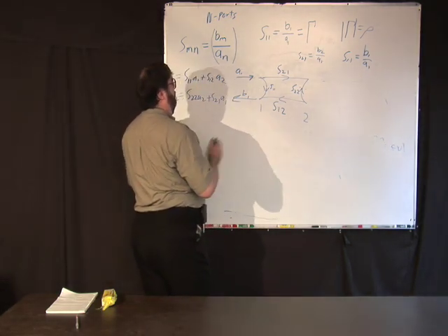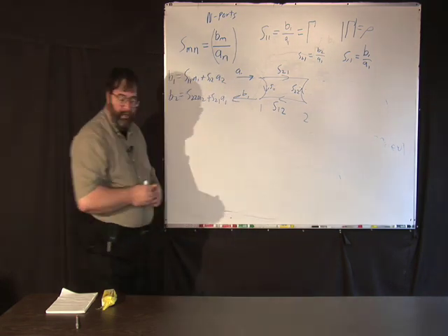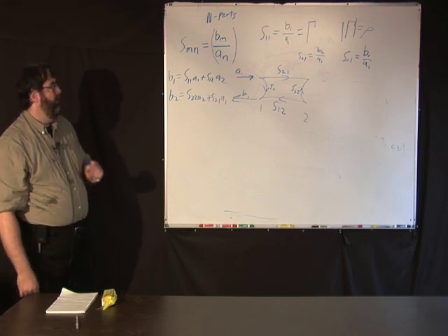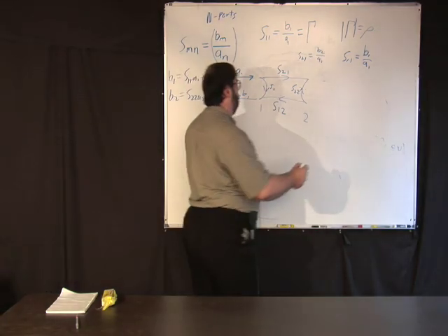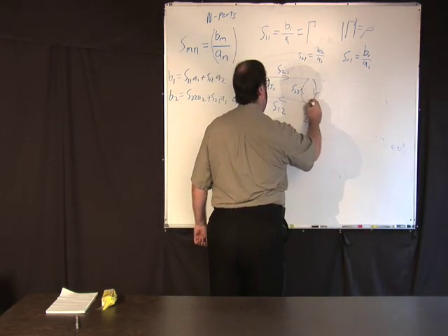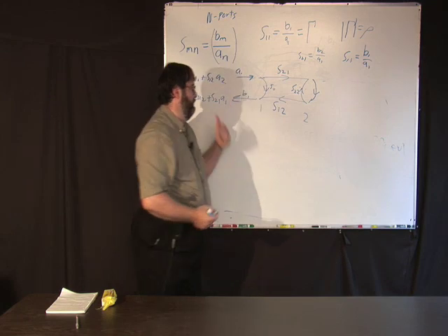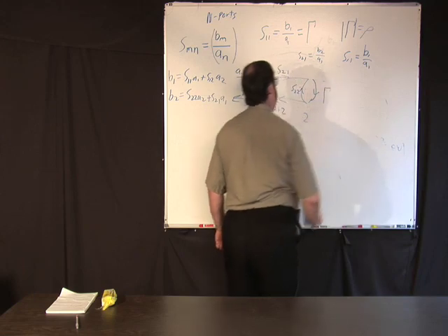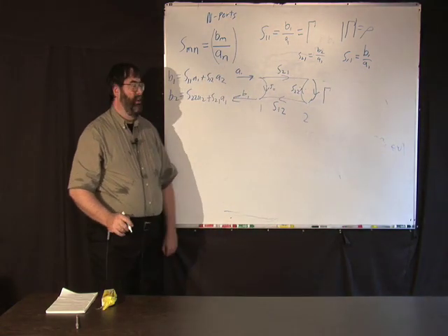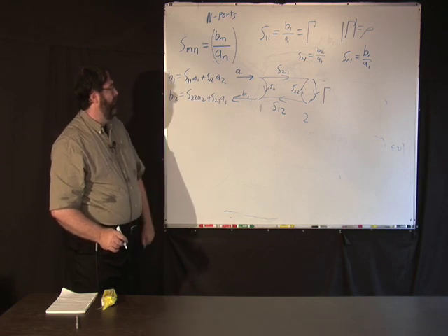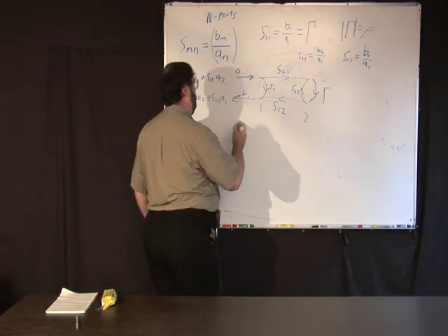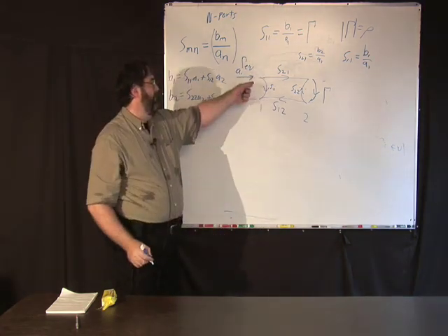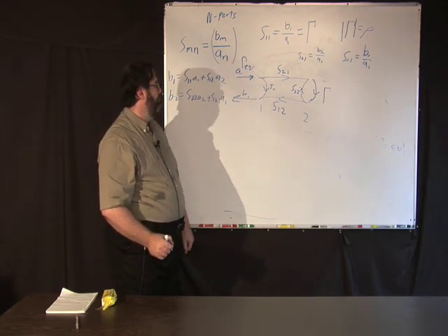But anyway, what's the next most complicated thing? We've done a one-port and two-port. You'd think it might be a three-port, but no. What happens if you put a one-port on a two-port? So you terminate a two-port device. It now becomes a one-port device, right? We'll call this gamma, just to make it separate from the others. So now it's a one-port device. Well, what do you want to know? What you might want to know from this is what is gamma equivalent? What kind of one-port device does this look like?